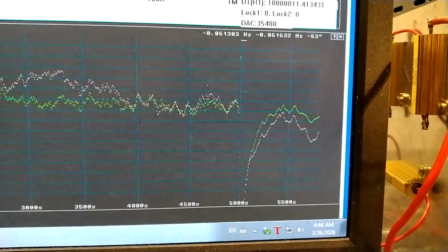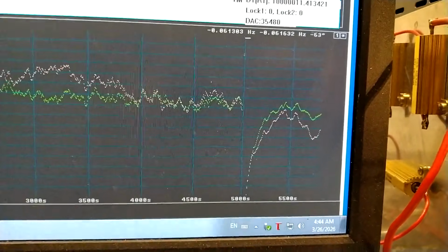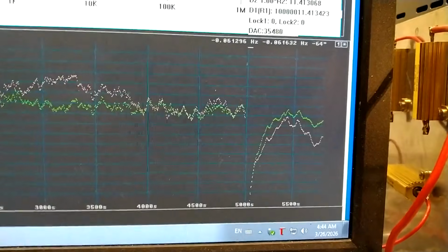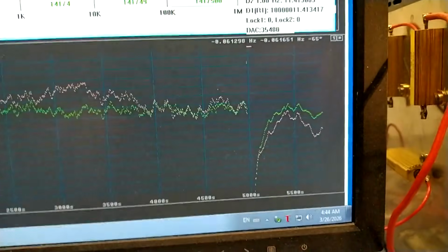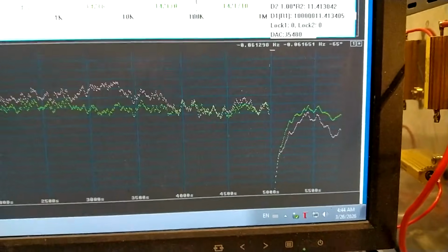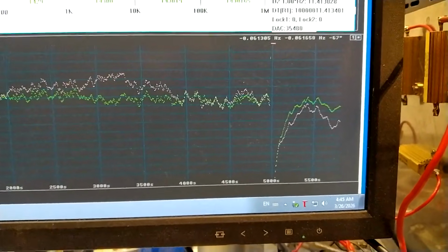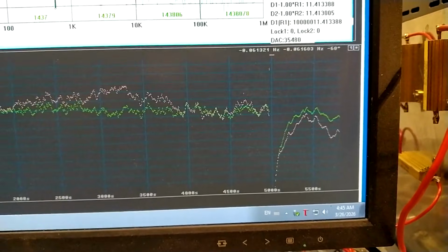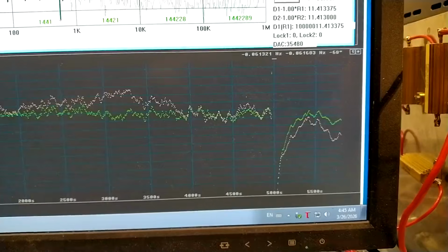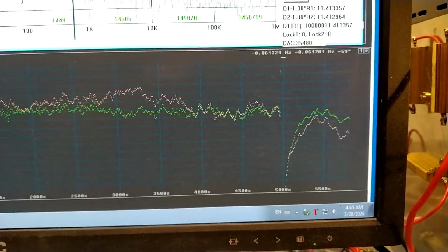And I can try to make the time constant even bigger than this, and then will probably the low frequency oscillations grow, because the instabilities of my 4-crystal oscillator will not be corrected fast enough by the frequency shifted rubidium source.